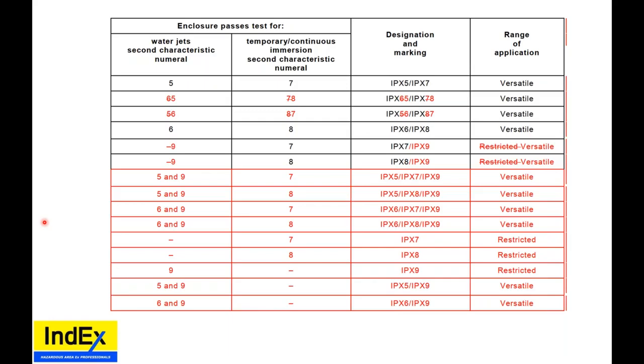Does this relate to flammable gases? Well, flammable gases, if you had a potential source of release and you defined it a hazardous location, hazardous area, then you choose your selection of your equipment, your minimum IP ratings, according to the standards: IP54 for nearly everything, IP44 for Ex p, IP20 for Ex i. But would you only accept IP20 for intrinsically safe apparatus outside? Is IP54 enough? Even in dry locations, IP5 would not be enough in many instances. Dust will get inside. Is your facility to last 5 years, 10, 25, 40? Certain ones in Australia have 40-year design lives.